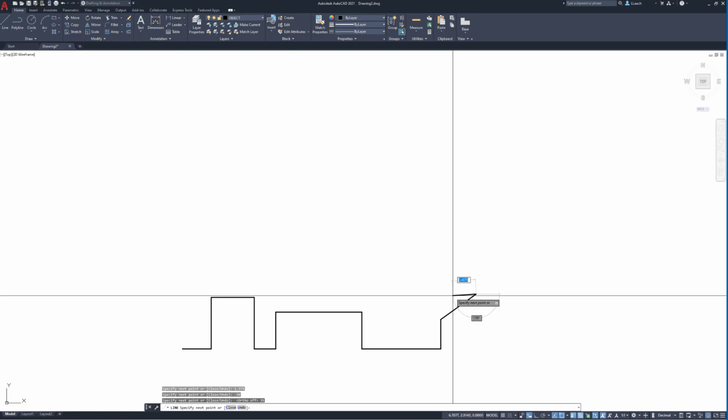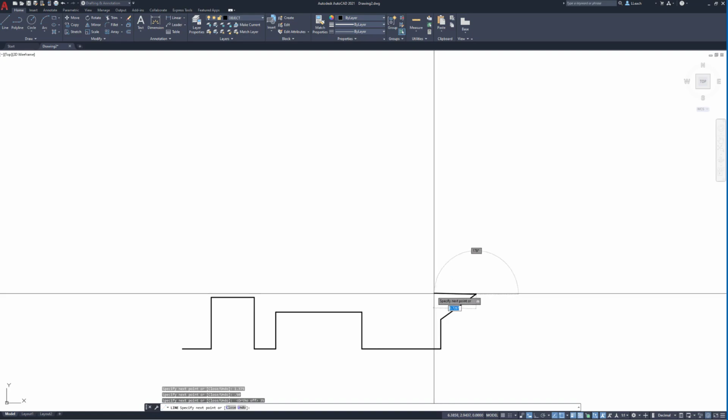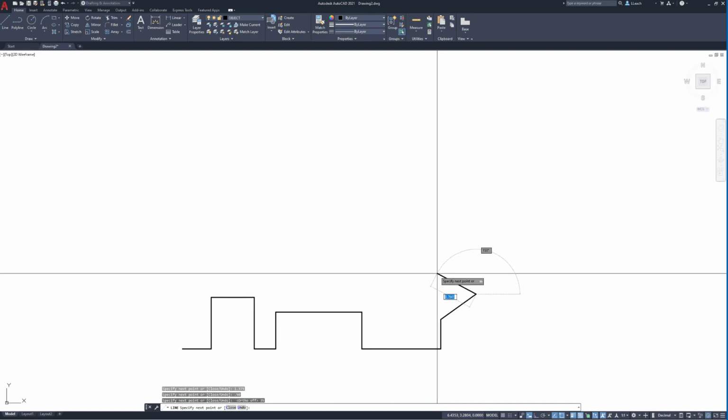Now I'm going to go back over. Basically, it's just a mirror image of this, but I'm going to draw my mouse over to the left and a little bit up. Again, it's going to be 0.75. Press the tab key. Now you notice they give us an angle of 35 in that one direction, but AutoCAD measures angles from the right. So I'm going to need to figure out what that is. That's going to be 180 minus 35. So the angle I'm looking for here is going to be 145. Press enter.